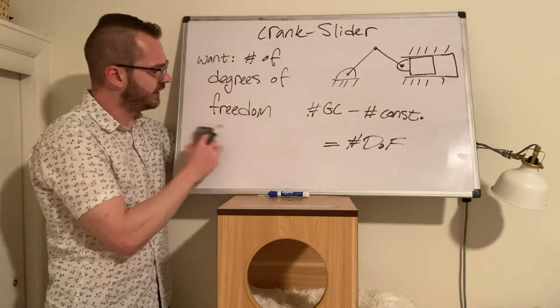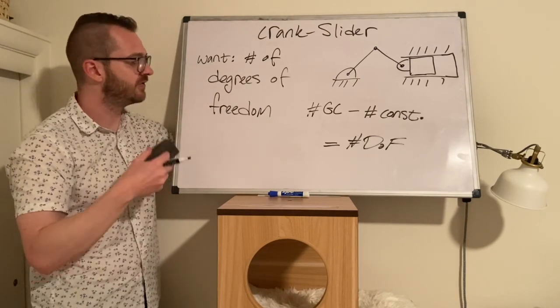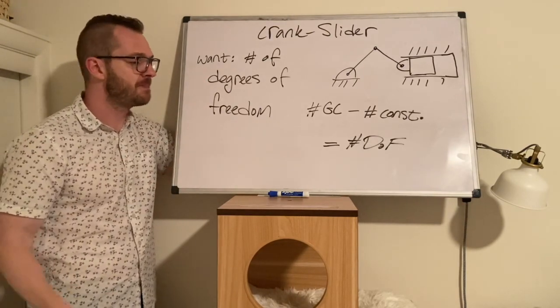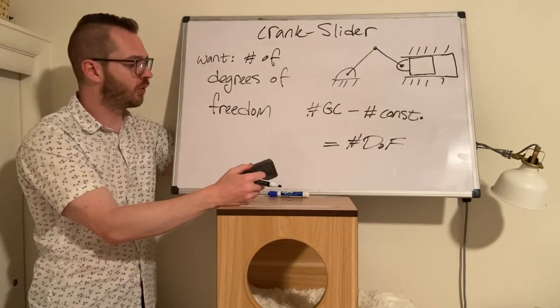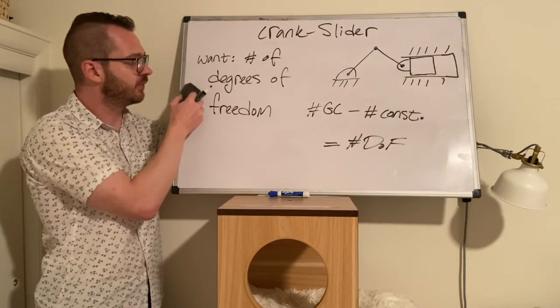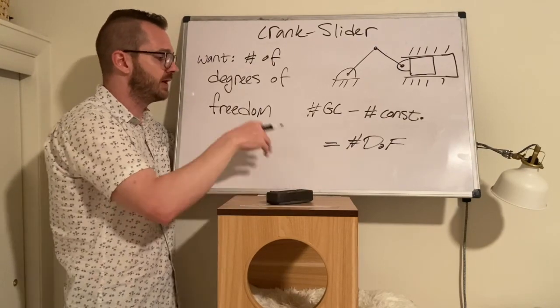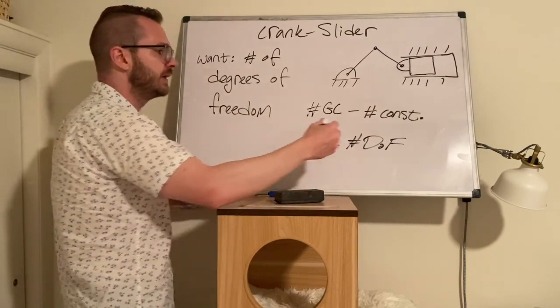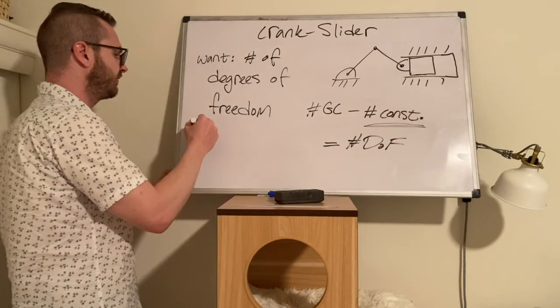So the goal then, when you read a problem statement that says, determine the number of degrees of freedom, maybe you can look at this thing and say there's 1 independent coordinate. That's not good enough. This statement where it says we want the degrees of freedom, that means you have to follow a certain process. Ultimately, we're looking for the constraints, but the process is really this.